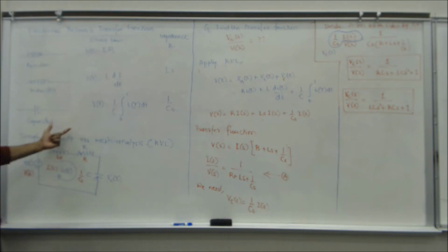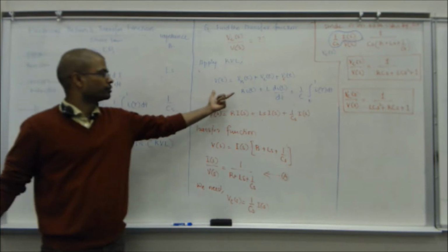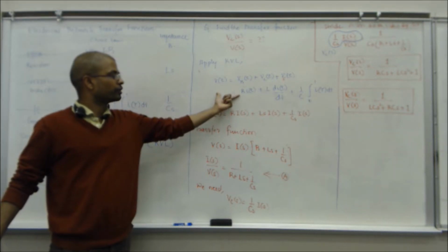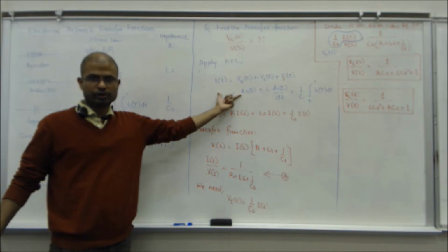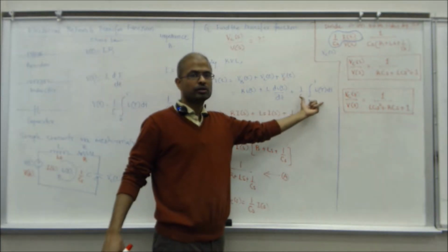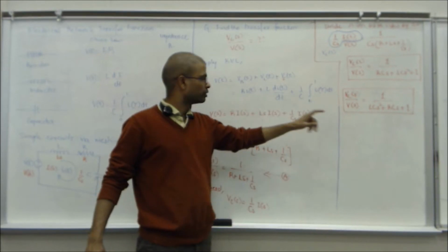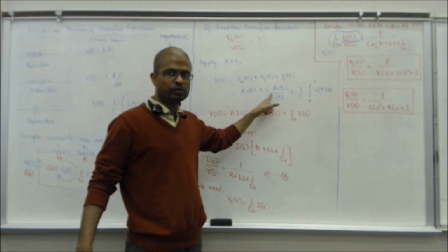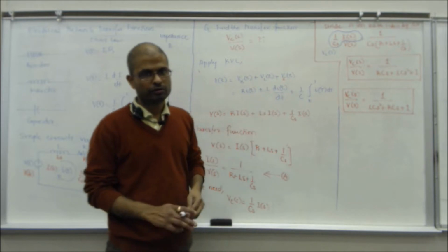If you're not taught Laplace transforms and you are asked to develop the input-output relationship, or the mathematical model of this, you would do this. Do you see this as a differential equation? You can look at this as either first order or second order because there is an integration here. If you take the derivative throughout, this will become a double derivative, so it will be a second order differential equation.